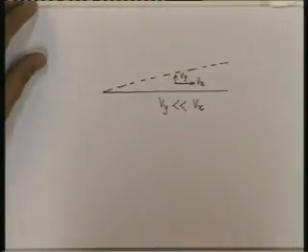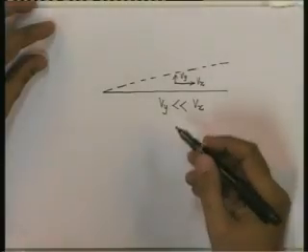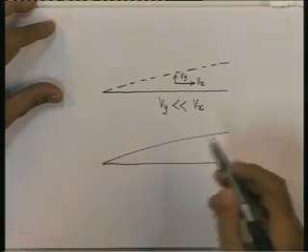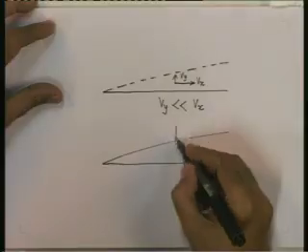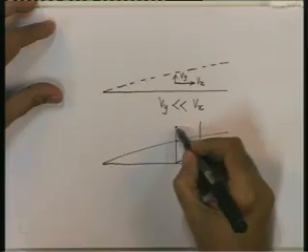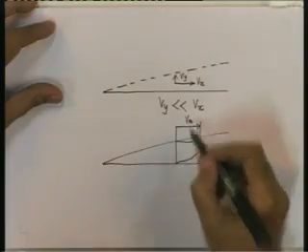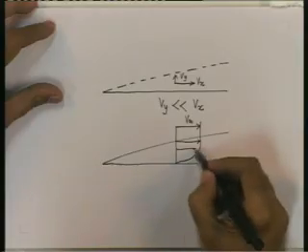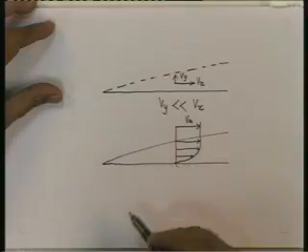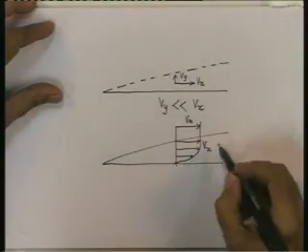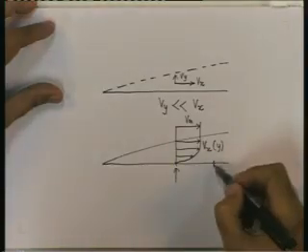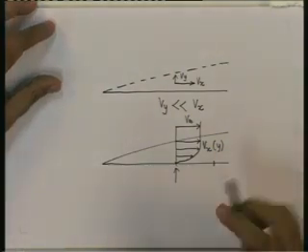So for example, if in the same boundary layer I take, say, the velocity profile, this is Vx, so it reduces from V infinity in the free stream to 0 at the wall, and this is a function of y at a particular x, but at a different x, Vx will have different values even at the same y.